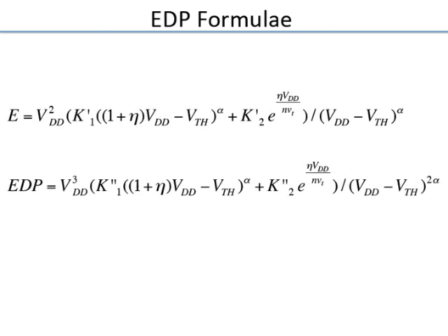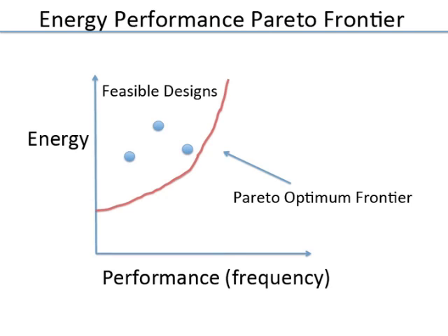Of course, you can do a brute force search. Suppose you want to find the best VDD, you can set it up, do a brute force search for different VDD values and measure and so on. But this allows you to get close to the answer, and then around that answer, if you want to do further optimization, you can play around and get the values. So in the quest of scaling VDD, what is the right VDD to use? That is where we are going with all these discussions.